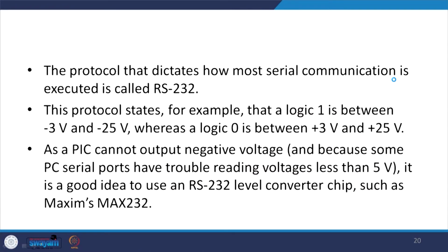Now, the protocol that dictates how most serial communication is executed is RS-232. The protocol states, for example, that a logic 1 is between minus 3 volt and minus 25 volt, whereas logic 0 is between plus 3 volt and plus 25 volt. Okay. As a PIC cannot output negative voltage, and because some PC serial ports have trouble reading voltages less than 5 volt, it is a good idea to use RS-232 level converter chips such as the Maxim MAX232.